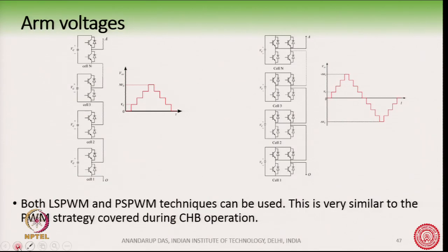in the cell. So, okay, before I go there, just let me recap that the arm voltage from the half bridge is unidirectional in nature, while the arm voltage from a full bridge is bidirectional in nature. Okay. So, this is what is going to be produced from the arms. Okay. So, this is what is the desirable arm voltage. Of course, we will have a PWM here, and this PWM typically looks like this here. So, there will be switching actions here.